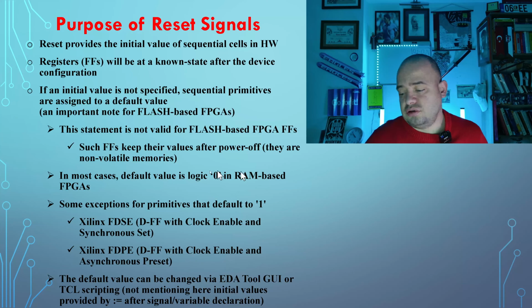If it is a synchronous one, the setup and hold constraints should be fine because it's a synchronous input like any other signal read in your process. Those inputs shall have positive setup and hold slacks.